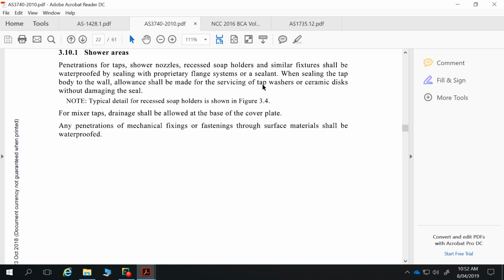However, typically what you do in practice is you produce sheets of wet area details and then attach those sheets to all of your building projects. Within this subject, what you're required to do is, for project 2, provide wet area details. You produce your wet area details based on AS 3740. Now you're only required to produce those wet area details for a limited view of your building.